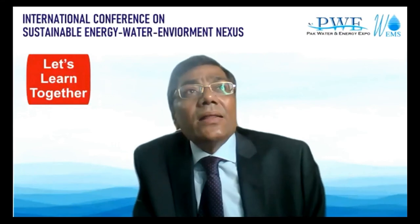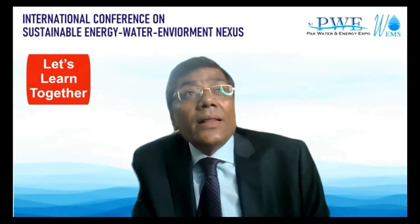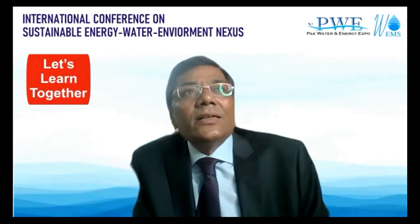Soft water is basically used for washing laundry and showering. First of all, it should be tap water with less than 1000 TDS, and then it should be softened water, because calcium, magnesium, and iron must be removed. When we use the ion exchange process, we remove the calcium, magnesium, and iron. Hard water creates stains on the cloth, your soap doesn't dissolve much, and detergent consumption is high.